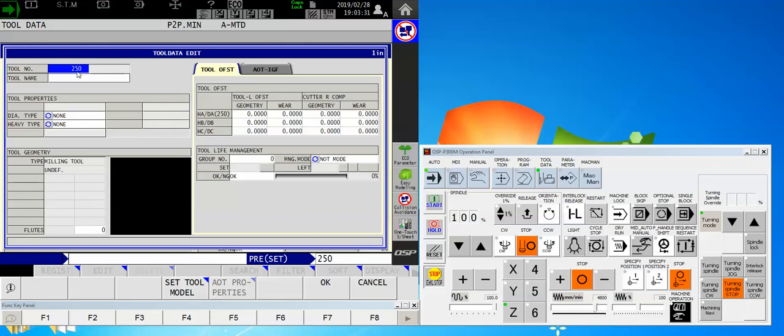So by naming this shell cutter something well out of the normal range of operation, if I pull this tool out of the machine and set it in a cart and go back to it in 3 weeks' time, I can stick it back in the machine, express to the machine that I installed tool 250, and its previous offset will still be in my data page and will not have gotten erased, unless of course I had a different tool 250 for some reason. I have the opportunity, if I want, to apply a tool name. We'll call this a shell mill, give it a size.